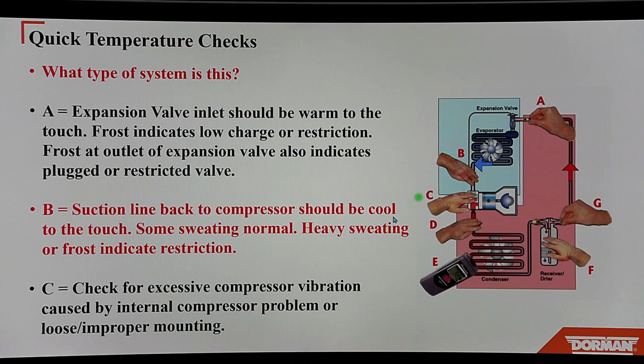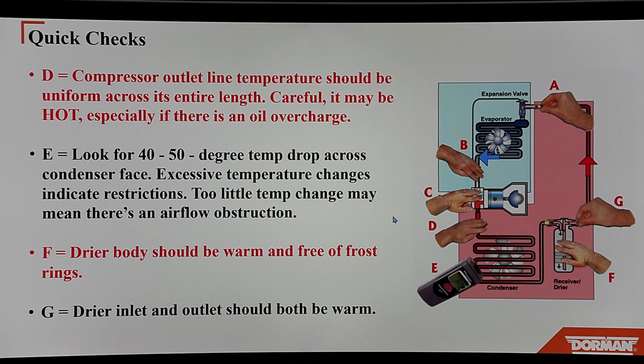C, at the compressor, you shouldn't feel any big vibrations. D, the compressor outlet should be pretty hot. Be careful, don't burn your hands. E, if you have a temperature gun, like a Raytek gun or a touch pyrometer, you should be about 40, 50 degrees difference side to side. Too little temperature change, you may have an airflow restriction.